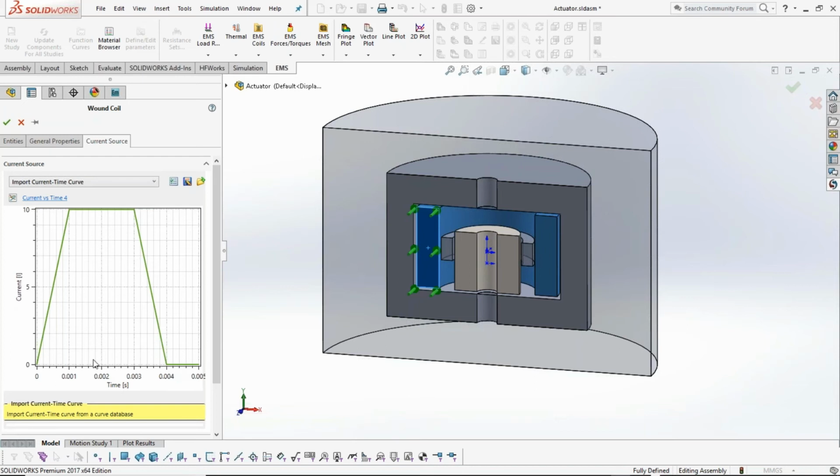So when I have this kind of excitation, obviously I save a lot more power in exciting this particular bistable actuator, and over a period of millions of operating cycles, you can see substantial savings in power. And that's one of the objectives of studying what happens under this kind of excitation. Would I still be able to actuate it under 5 milliseconds, which is a design requirement?